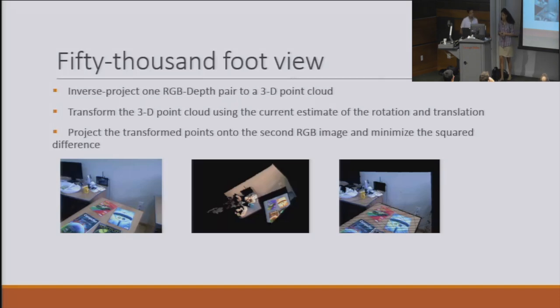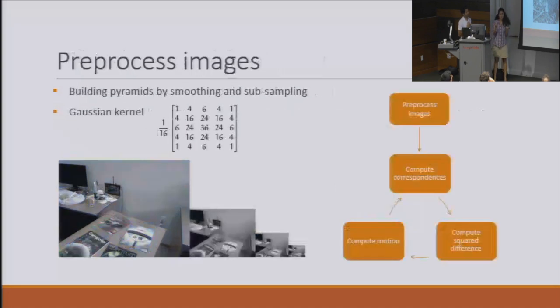So we process depth images and the RGB images. We convolve every pixel with a Gaussian kernel, and we downsample the images. At the same time, we also process depth images. We are only considering those depth values that lie in a certain threshold. And then we calculate image gradients using Sobel filters, which was just explained in the previous presentation. And so this is our performance.